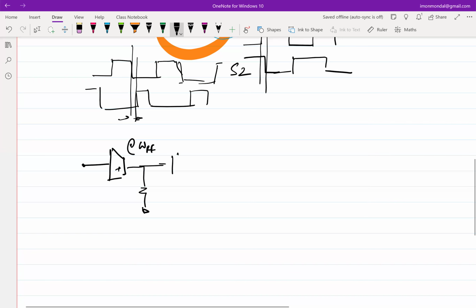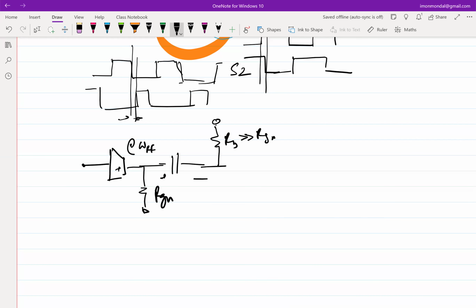So if I put an AC coupling capacitor sized such that the value of the impedance of the capacitor is much lesser than the effective Thevenin resistance it sees around it, right? So then this is a short at a single frequency. Then I can probably use an RB, which is much larger than this RGM. In this case, RB can be much larger than RGM without causing any loss of signal, or without causing any additional drop of the operating point, right? So you can have this.